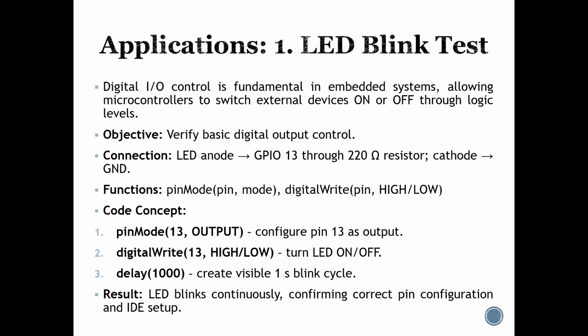The first test was a simple LED blink program used to verify Arduino's output control. I configured pin 13 as output and toggled it on and off every second using digitalWrite and delay. This basic test confirmed that the simulation environment and Arduino were working correctly.